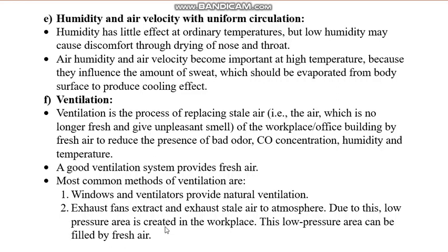When exhaust fans are removing the air from within, a kind of low pressure area is created, and thereby fresh air comes in. Okay, if the air is going out through the ventilators and exhaust fans, then through the doors and windows it will come in. Normally the hot air will be rising up, and the cold air will be down. And nowadays, you may have seen on the top of the factories, some rotating turbo ventilators are also being installed. Okay, that is also for ventilation purposes.